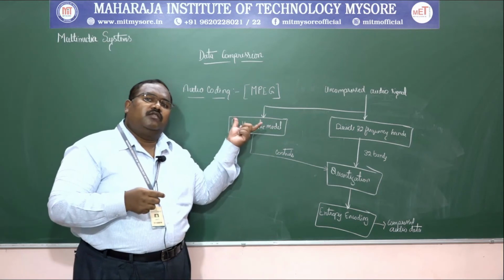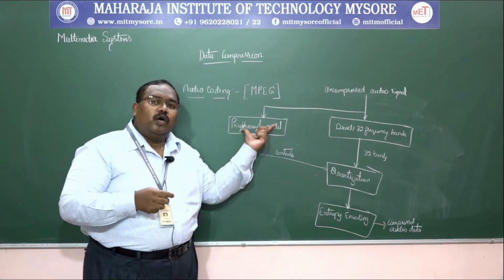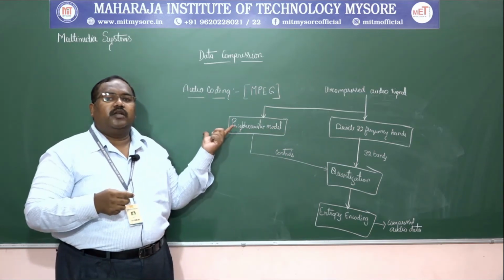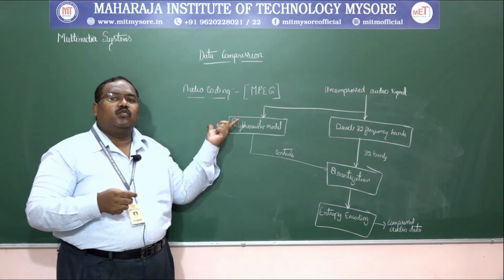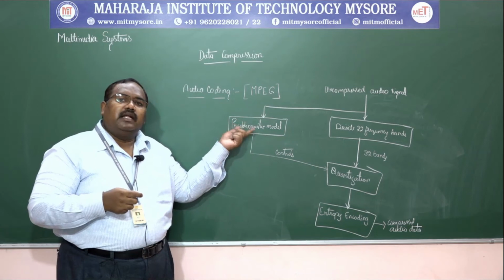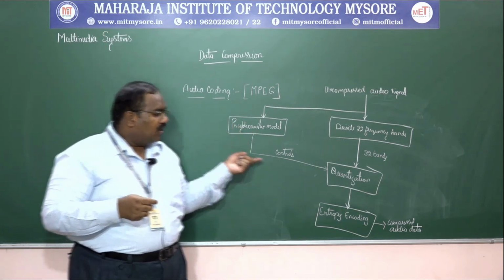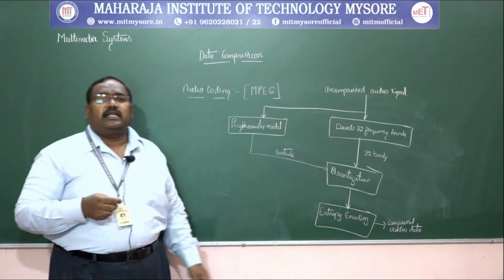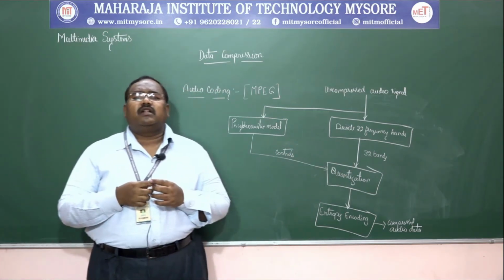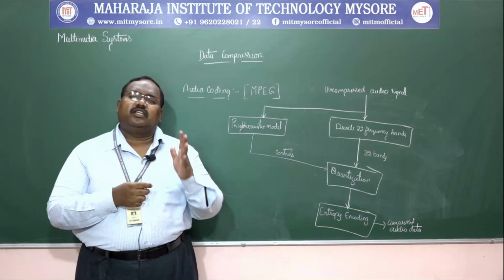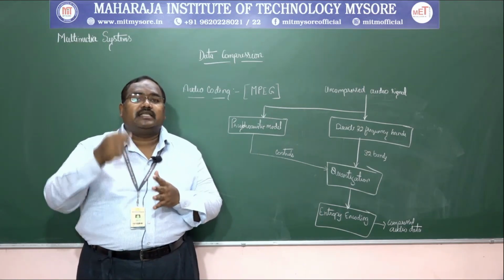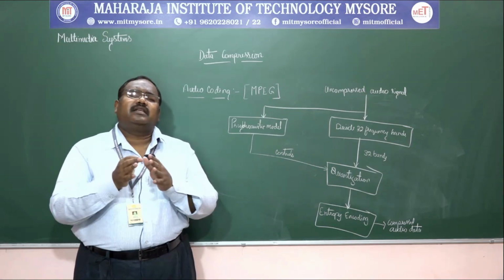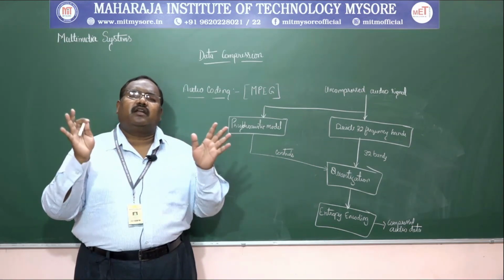In order to derive those things, we need one more process in parallel to the division of the audio signal, where the FFT is applied, and those signals or information or controls are fed in before the quantization. For higher noise levels, a coarse quantization is performed. For lower noise levels, the result is a finer quantization.